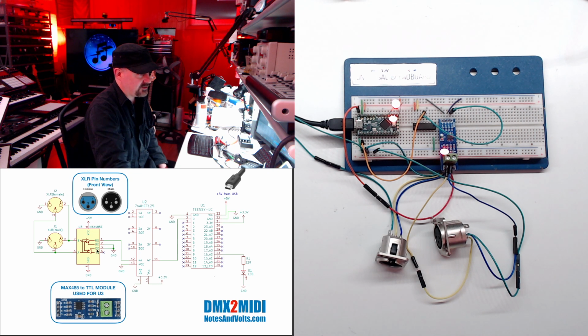The transmitter pin is disabled when you put ground into it. That's convenient because we only need one signal to disable one pin and enable the other. If we flip this to plus 5 volts, we would then enable the transmitter and disable the receiver. So we're going to connect both those pins to ground, and that basically just enables our receiver pin.